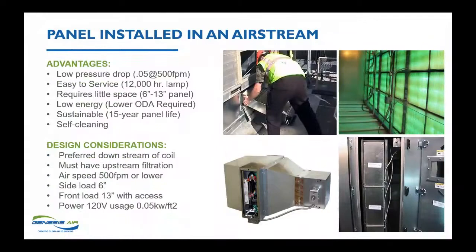On the right hand, there are some pictures. I mentioned the static pressure drop was low. It's been measured at 0.05 at 500 feet per minute. One of the questions that often arises is, what service does it take? The panels themselves are sustainable. They last 15 years, but the service is every 12,000 hours or 15 months. But because of operating budgets, consider it an annual replacement of the lamps.